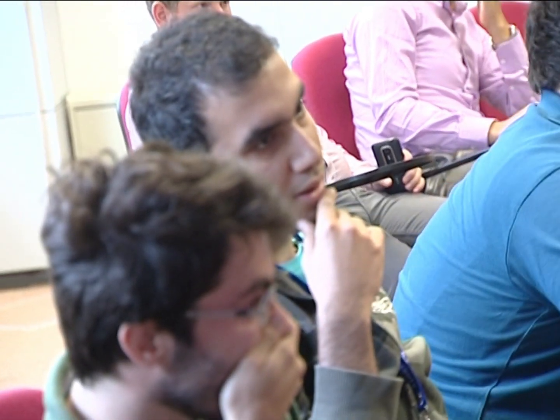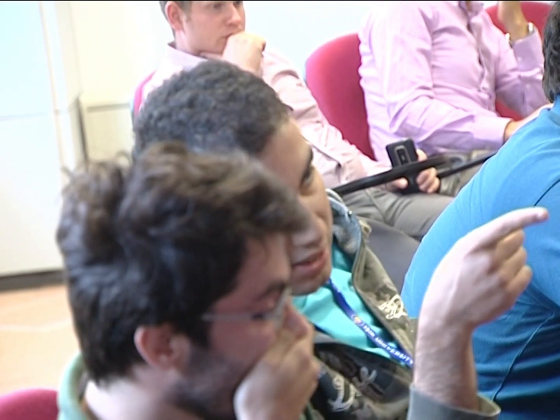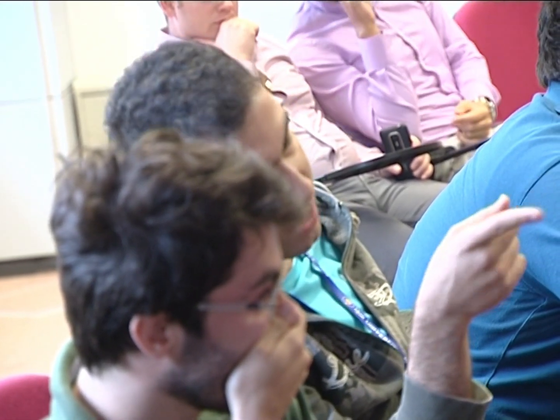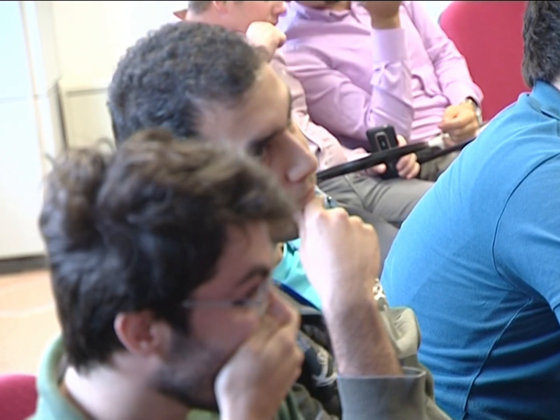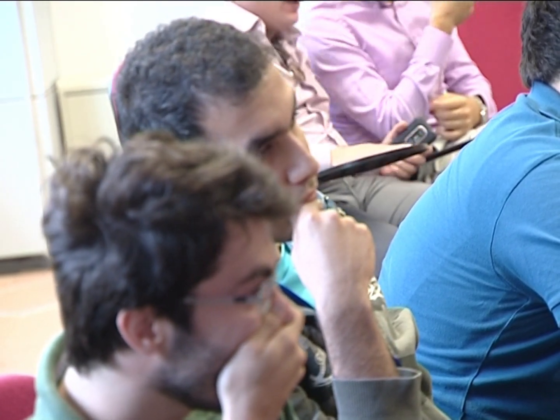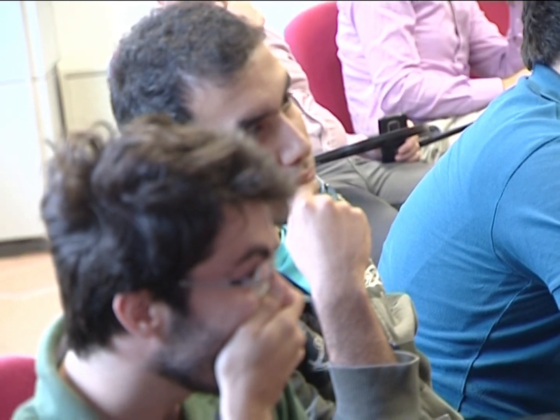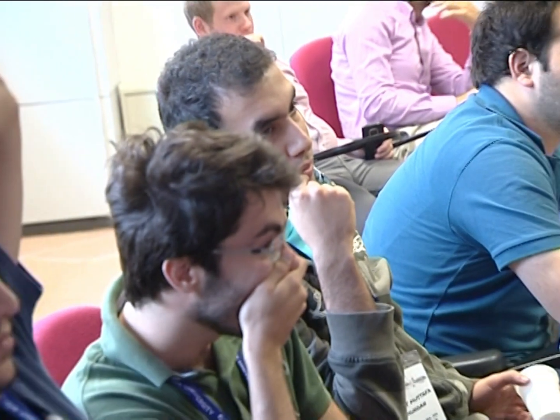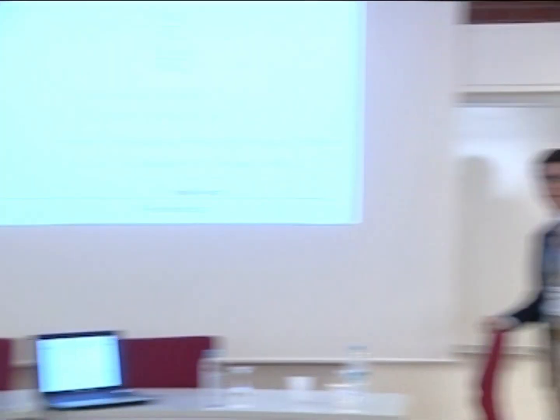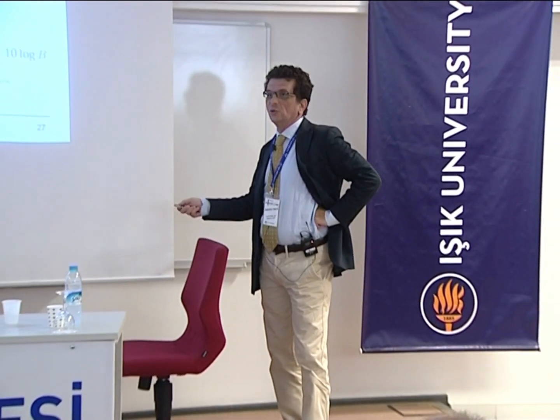SNR is a given number, a minimum. Why did we write it as SNR minimum? Because this is what the standard specifies. It means that it requires this minimum SNR in order to elaborate in the digital processor in a correct way. Of course, that's the minimum acceptable, so if it's larger than that, it's okay. So this is the specification, minimum signal-to-noise ratio, which tells, given the noise figure, what is the sensitivity that you are required.